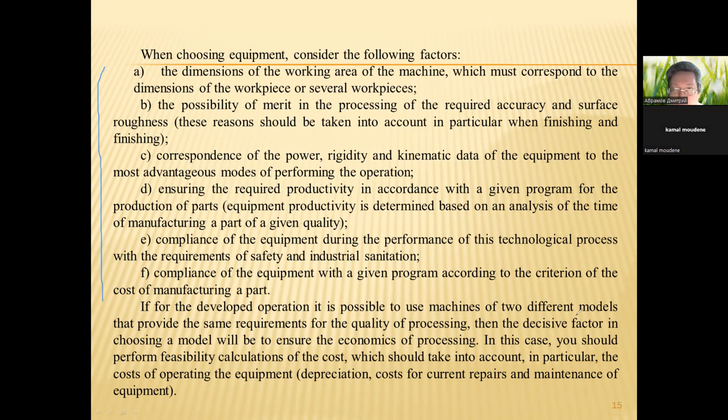A. The dimensions of the working area of the machine, which must correspond to the dimensions of the workpiece or several workpieces. B. The possibility of meeting the required accuracy and surface roughness in processing. These reasons should be taken into account in particular when we have finishing operations.